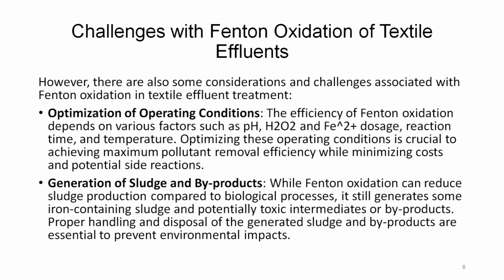The efficiency of Fenton oxidation depends on various factors such as pH, hydrogen peroxide and ferrous ion dosage, reaction time and temperature. Optimizing these operating conditions is crucial to achieving maximum pollutant removal efficiency, while minimizing cost and potential side effects.